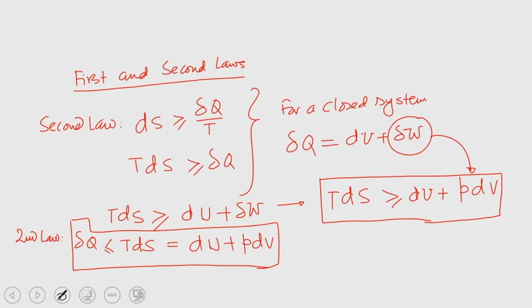What I told you in the last class is that this equation, T dS equal to du plus P dV, is valid for any processes, but we should be careful in applying it. If you would like to apply this equation for any process, then the equation has to be integrated over a reversible path, and the results of integration can be applied to any process. That is a very important point we should remember.